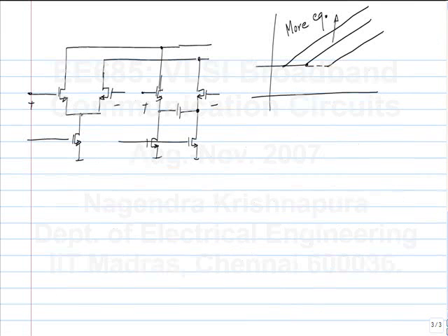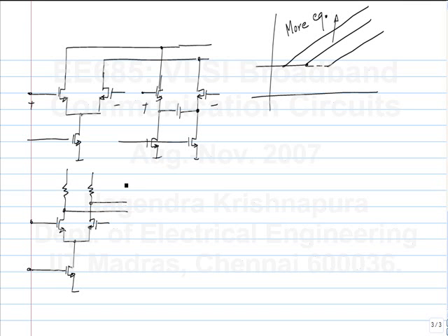cursor. So the trade-offs would be, let's say you start off with an amplifier like this, and let's say this is driving a certain voltage to the channel. I mean, channel meaning there is a transmission line terminated on the other side also with a resistance. Now, you find that this is not good enough, you need equalization, okay. This is an unequalized transmitter, and let's say this is driving 1 volt peak to peak, and it's not able to drive it properly, you need some equalization.